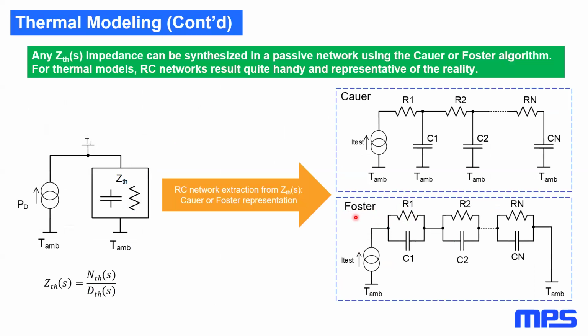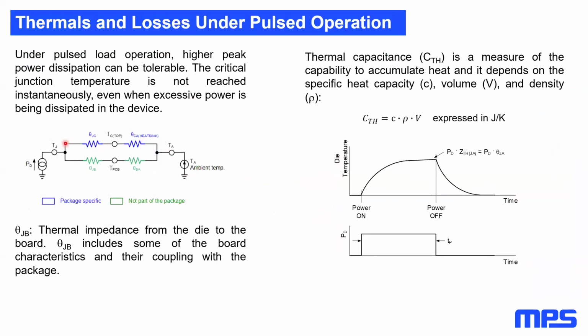Because you can see how here between every junction there is an RC in parallel, and every block represents the junction between two pieces of metal, or the junction between the die and the die attach, and the lead frame. Well, you can say very quickly, okay, this RC block represents the thermal resistance of that medium, which can be the die, which can be a metal, which can be the die attach.